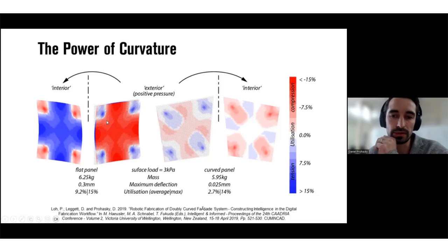So, a flat panel versus a curved panel on the right. Just a structural analysis showing 4 restraints at each corner, more or less, is demonstrating that you get about an order of magnitude stiffer panel when it's only subtly curved. So this one is about a 20-meter radius of curvature, and it's already exhibiting a significant reduction in deflection.